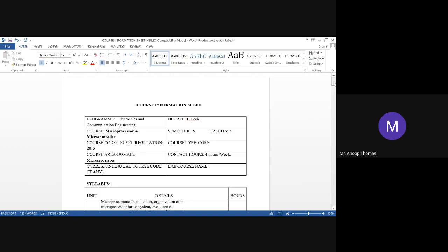It will also have an ALU, but the focus here is on controlling things, the number of ports, bitwise control, bytewise control, again different kinds of inputs and outputs, analog and digital inputs and outputs. So these are the things which are oriented in a microcontroller, and a microcontroller will have more modules compared to a microprocessor which is focused on processing.